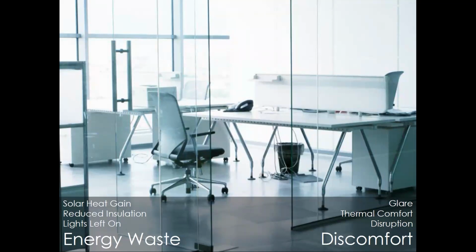Generally, facades with direct sun are always cooling. So you're going to see the energy usage here with using shades. Just because daylight reduces the need for electric lighting, it doesn't necessarily guarantee energy savings unless the lighting is properly managed to shut off or dim when not necessary. So all light eventually becomes heat when it's absorbed by an object or surface. So too much light is going to mean too much heat.